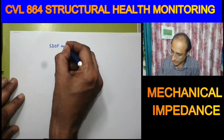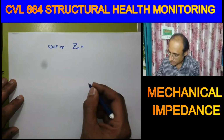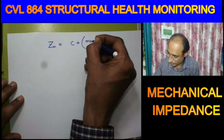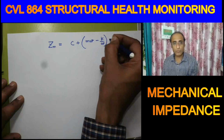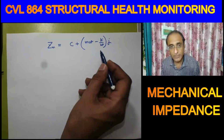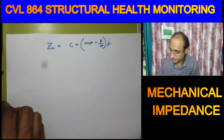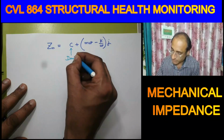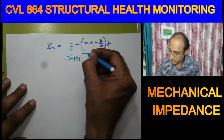The mechanical impedance Zm is equal to C plus (m omega minus k by omega) j. So it is a complex term now. It has the real component and the imaginary component. The real component is formed by the damping term and the imaginary component is formed by the combination of the mass and the stiffness terms.